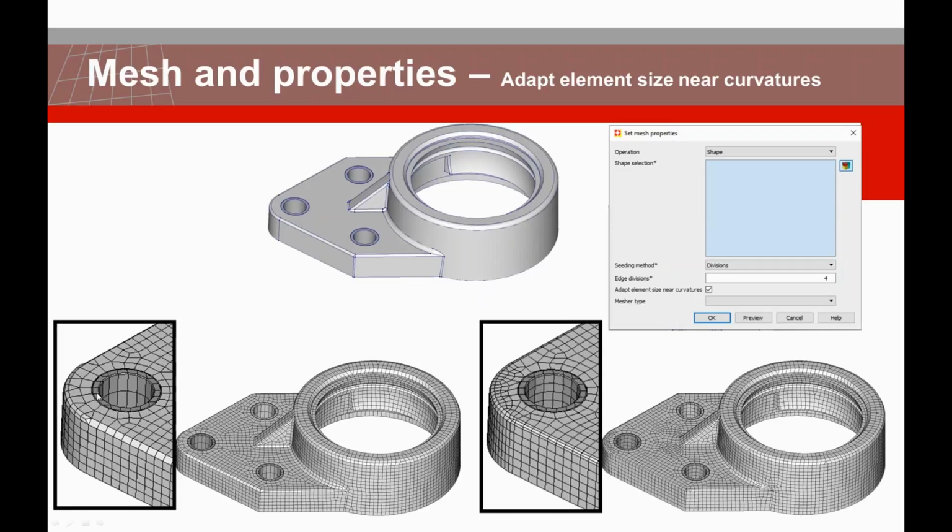This is good if you have some sort of pins, connections, these types of joints. If you have, then the program automatically refines the elements there. Therefore, if you have any stress localization in those areas, you have a very smooth transition of your state variables if you want to consider these types of sharp corners.